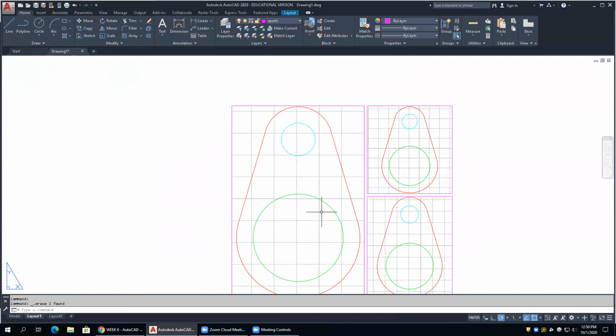All right, so let's go to the next page and we're going to take a look at zooming. So zooming is how we handle scale factor. Because now what's going to happen in paper space, we're going to plot everything from paper space, we're going to plot it 1-to-1.